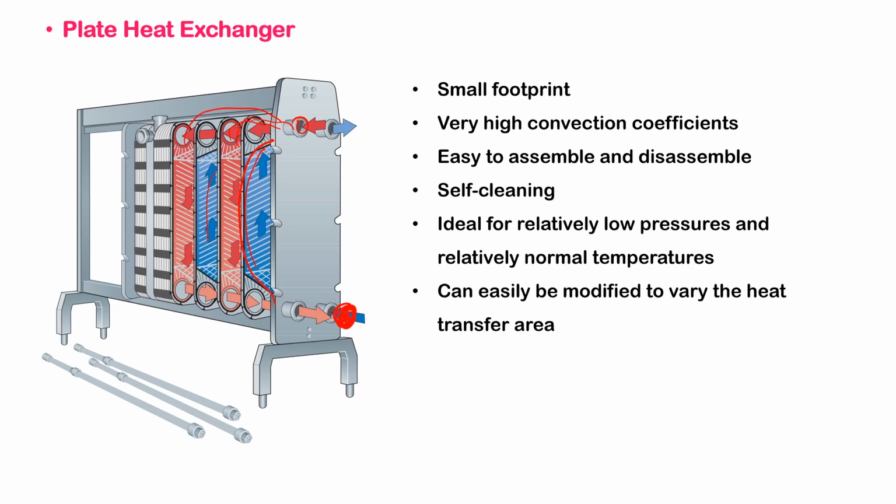So there is always contact between hot and cold fluid through the plate. Instead of a pipe wall, you have a flat plate that controls the heat transfer. And as I mentioned, you can easily remove one of these, so it is not difficult to do so.